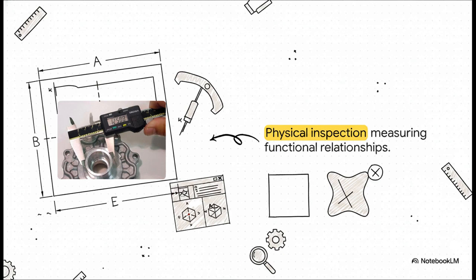It is incredibly easy to just pick whatever you want to measure from a mathematically perfect CAD model, but if the physical datums you've selected aren't actually consistently measurable on the real part, maybe the surface is way too small or it's inherently unstable, that's going to cause propagated measurement errors. The result: perfectly good, functional parts are going to look like scrap on the inspection report.